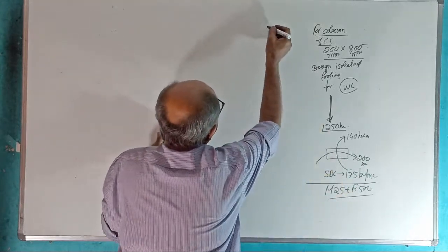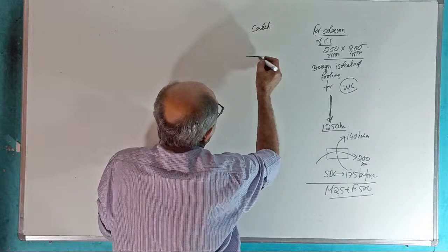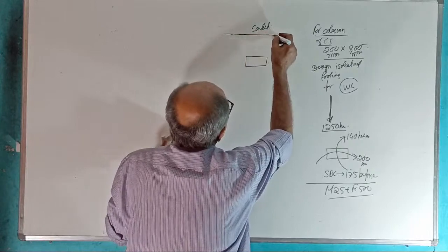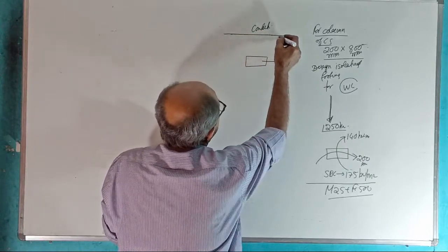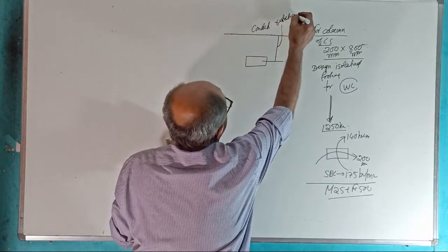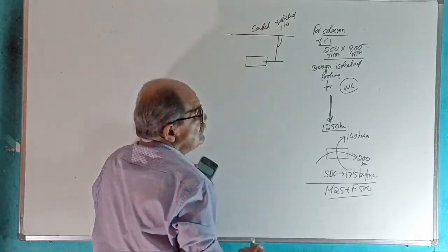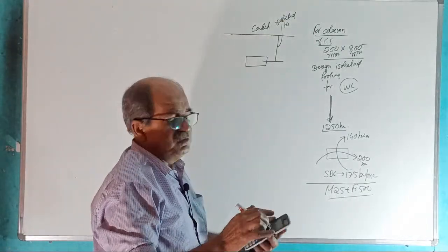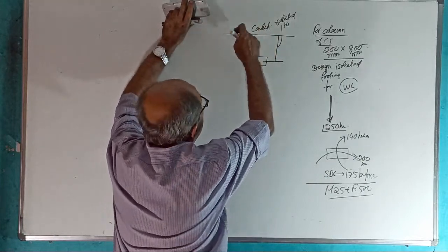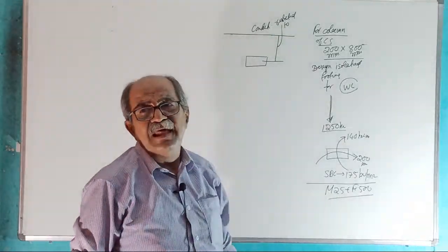But remember, there is a condition. The condition is that this is the column. When you provide a footing, there is a boundary line here. From the center of the column, this distance is restricted. It happens so many times. The restriction can come lengthwise also. Restricted to means not more than. The reason for the restriction may be that another footing comes here, or a boundary problem is there. So one restriction is fine. If a double-side restriction comes, then you have a problem.